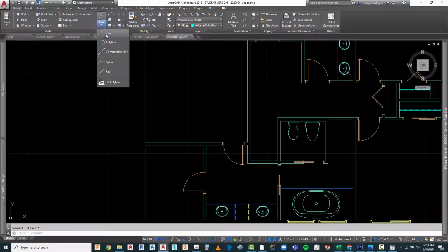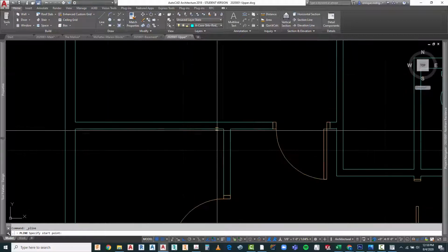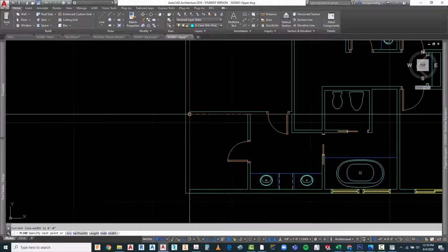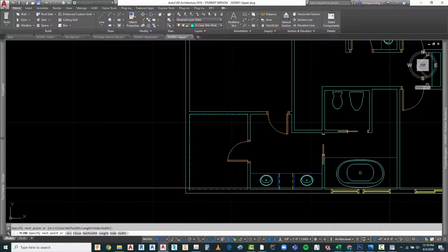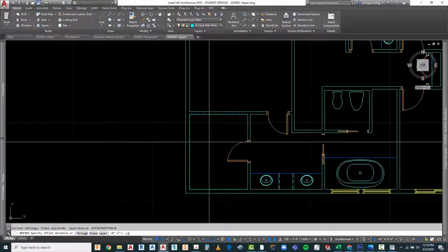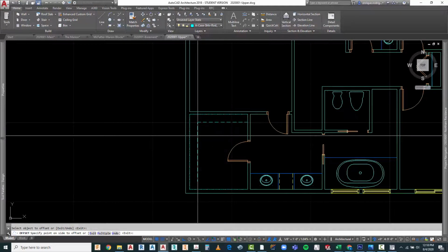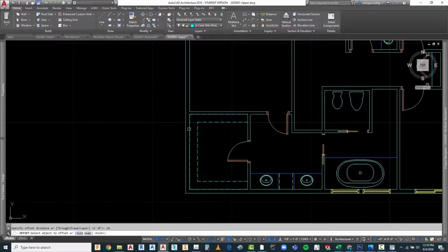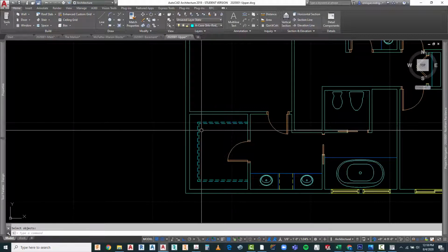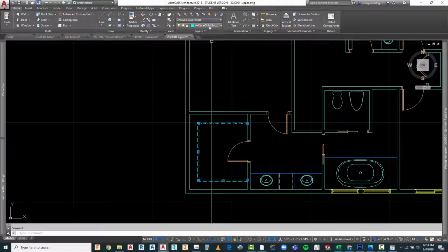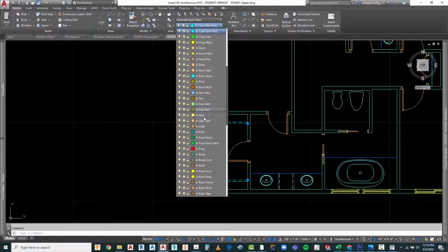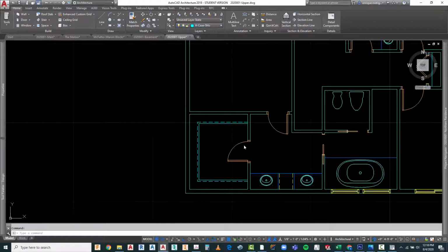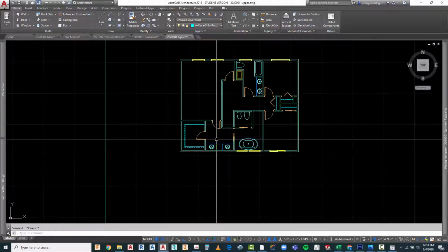So this time I'm going to go ahead and go to polyline, and I'm going to mark this off like that. And I'm in the AK shelf rod, so this is going to represent the rod, so I'm going to offset that 12 inches. I'm going to offset it again 14 inches. That's going to represent the shelf. I'm going to delete what we're using there, and then I'm going to take that one and change it to its proper layer. So I'm going to go back to AK shelving, and there, that's located right in there. That looks pretty good.